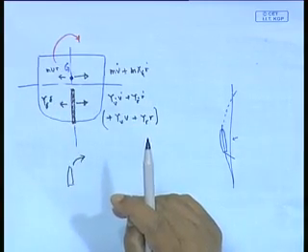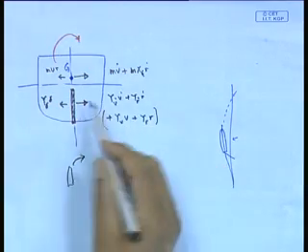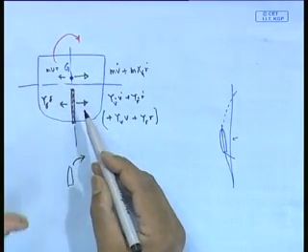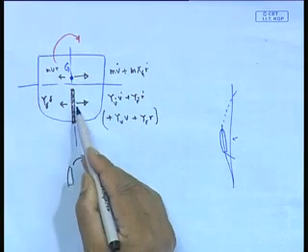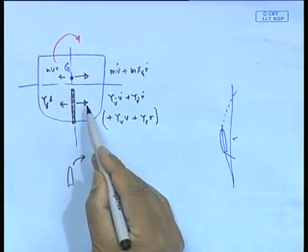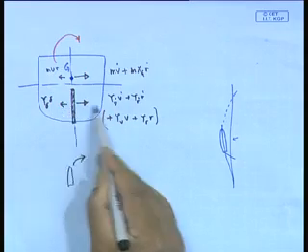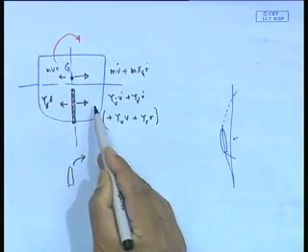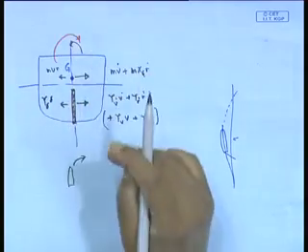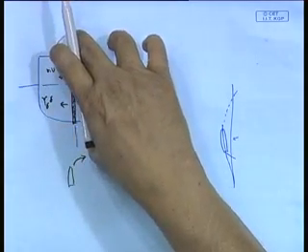As a result, I have more net force. I'll establish this relation, and we will even do a problem. This part of the force in the third phase is larger than this part, which means there is a net force on this side. Then the net moment is on the other side. So the ship turns on the other side.